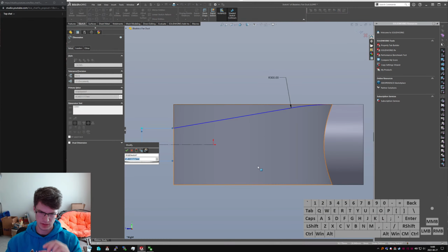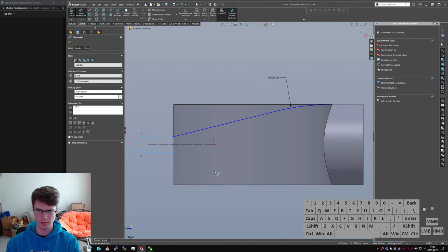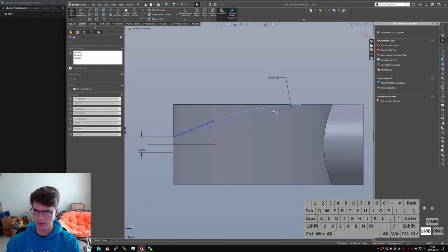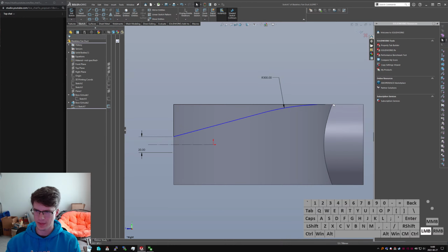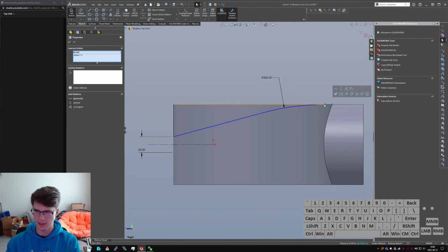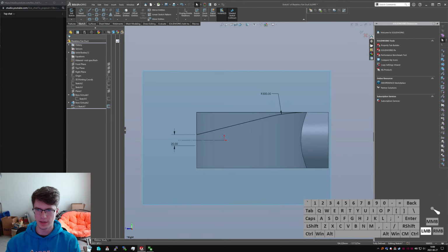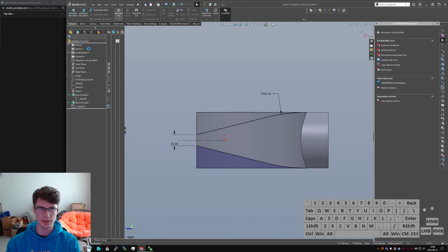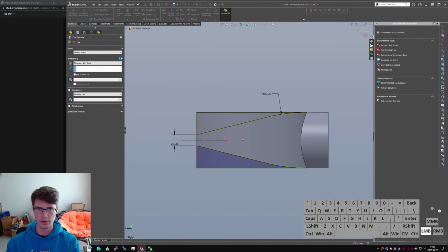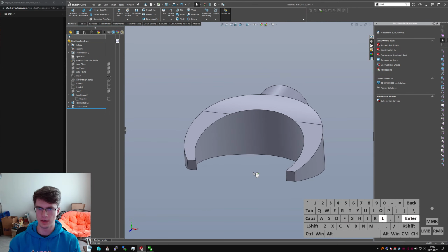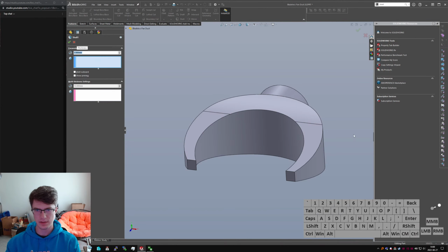Make this 20 millimeters, is probably about right. Oh, why are you? Ah, it made itself coincident to that line instead of to this point, which is what I wanted. So now I can select all this and say, please mirror, features, extruded cut, through all both. There's a duct. Now I can say shell to the tune of about 3 millimeters.